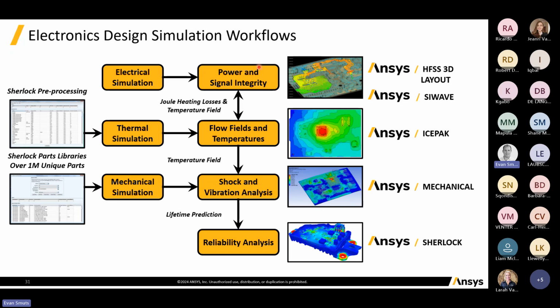So we can bring in things like, you start off at a very basic electronic level, looking at power and signal integrity. That invariably feeds into a thermal model, because all the losses in the boards will create some sort of heating effect in the board, so that we can take that temperature profile, bring that into Sherlock, and get a much more accurate temperature or thermal analysis of the components.